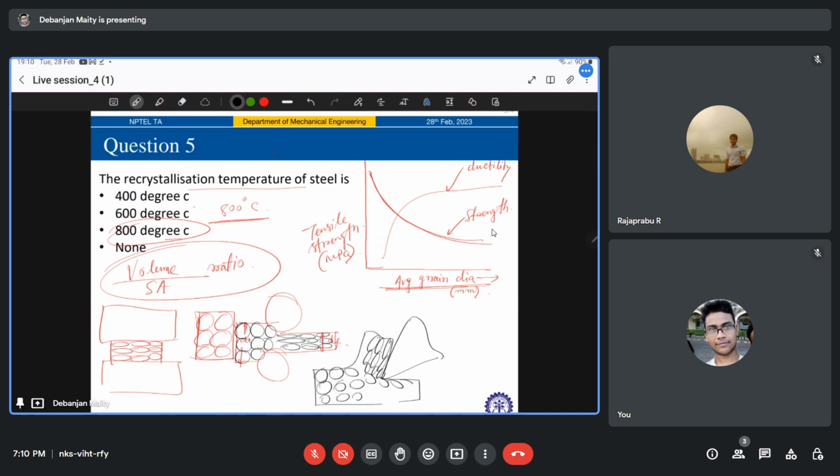Now, what does this figure basically show? This shows how the grains are deformed by various mechanical working processes. You can easily see that the effective grain size is reduced because the surface area of each grain increases, right? So whenever you are deforming the material, surface area increases, correct? So the effective grain size is reduced.